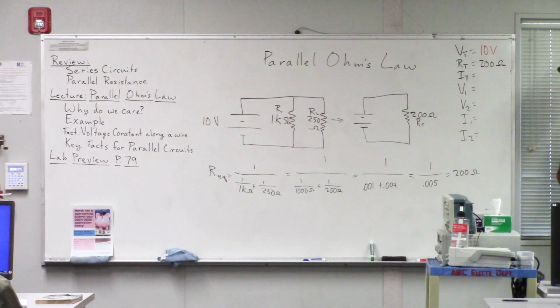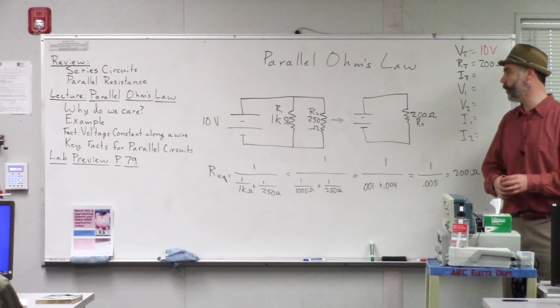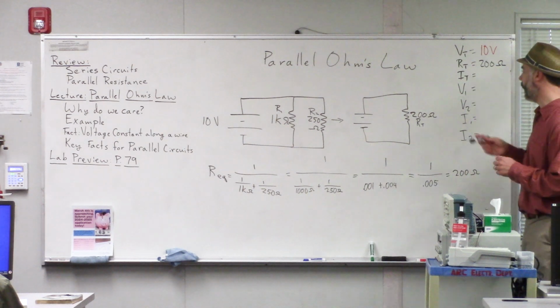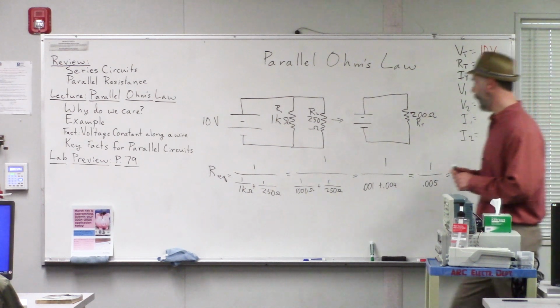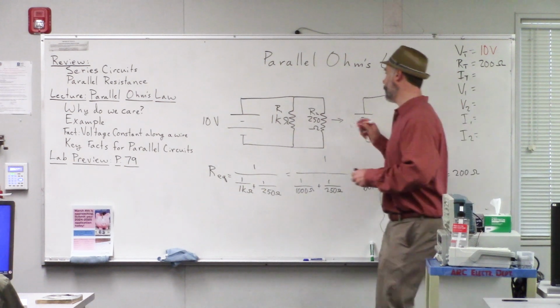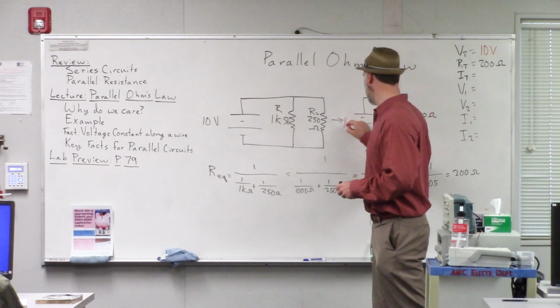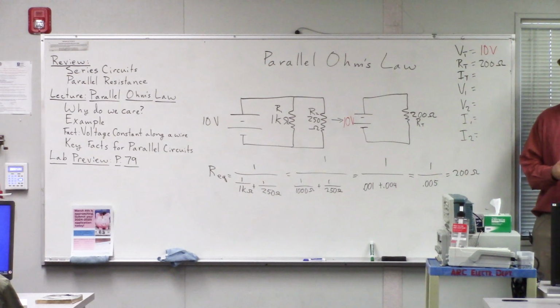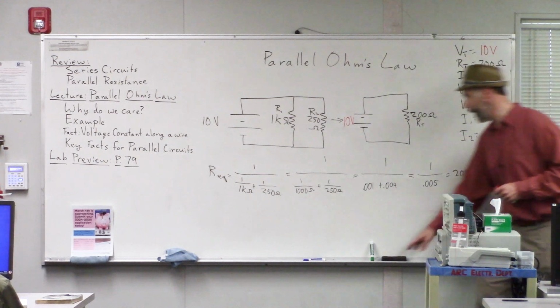Now we have to figure out what to do next. That's really the hardest part of these problems, is figuring out where to go. What's your next step? So anybody want to venture a suggestion about what we could work on? I total. Okay, yeah, we can work on I total. Perfect. And so how can we figure out the total current? Ohm's law. Yeah, Ohm's law, exactly.